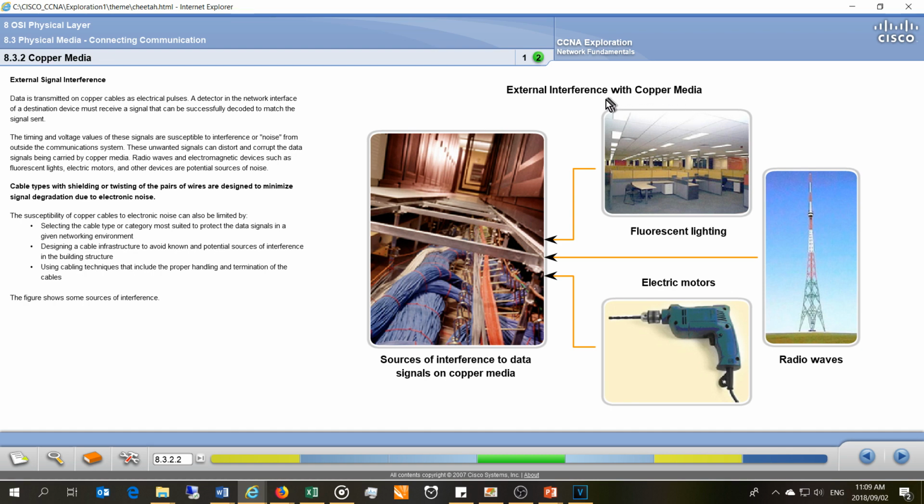And also certain electrical devices give off noise. Electrical noise, you can see here this is fluorescent lighting, and it tends to provide a flicker at the power frequency. So if your country is using 50 hertz, well, then it will flicker at 50 hertz. If you're using 60 hertz, it'll flicker at 60 hertz, and that also causes noise on these cables and through our devices.